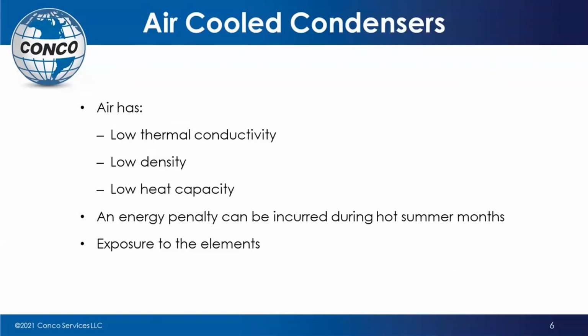Air-cooled condensers, what are the advantages? What are the disadvantages? Well, the big advantage is that you can put them anywhere. You don't need the water. But it has some real disadvantages, some things that you've got to remember. And this plays right into the cleaning of the unit. It's got a low thermal conductivity. It's got a low density and a low heat capacity. What does that mean? It means that the transference of heat from the steam over into the air itself is less than the transfer of heat into water. Water is more dense. It's got a higher thermal conductivity. And so you need less of it to cool down the steam. Air-cooled condensers, we need more air.